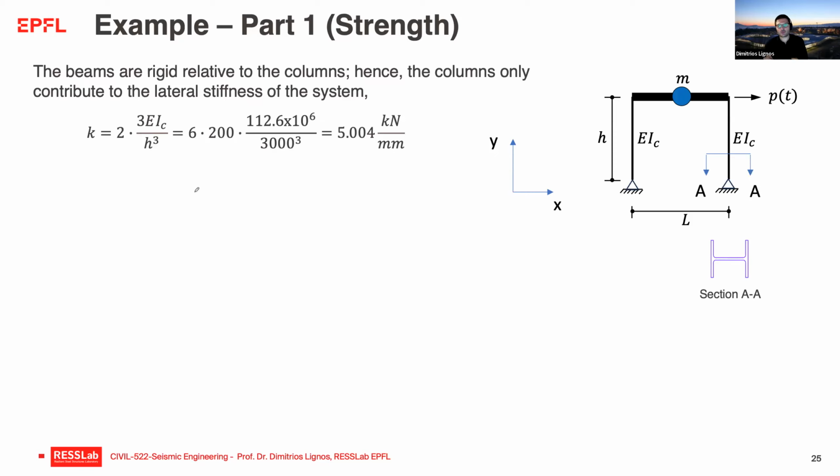So to answer this question, first we're going to have to estimate a few things, and in particular, because I need the seismic action, I will have to compute the corresponding period of the single degree of freedom oscillator here. And of course, to compute the period, I'm going to have to estimate the mass and the lateral stiffness of my oscillator.